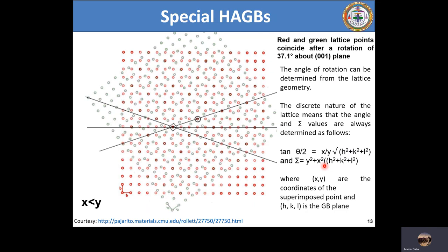It can never be even. If you observe very carefully, I've been only talking of sigma 1, sigma 3, sigma 5, sigma 7, and sigma 9 boundaries. Of course, people have even gone up to around sigma 13, but in real terms, a sigma 13 boundary doesn't make much of a difference in a microstructure, is my personal opinion, because a sigma 13 boundary means that only every 13th lattice point between the two adjacent grains is in perfect coincidence with each other.